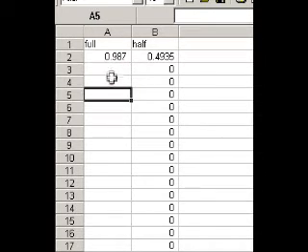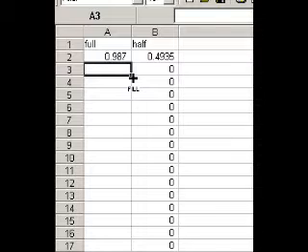I can add a few numbers, and the main reason why halving the value is important and helpful is because the origins of most of the objects we're going to work with are central, and to move them anywhere we need to overcome that distance to find out where that edge would be. So if there's a cube that's 2 by 2 by 2 and you need to move it across 3 meters, you first have to find out what half of its width is to find out the edge where that will be, which is pretty easy when it's 2 by 2 by 2.